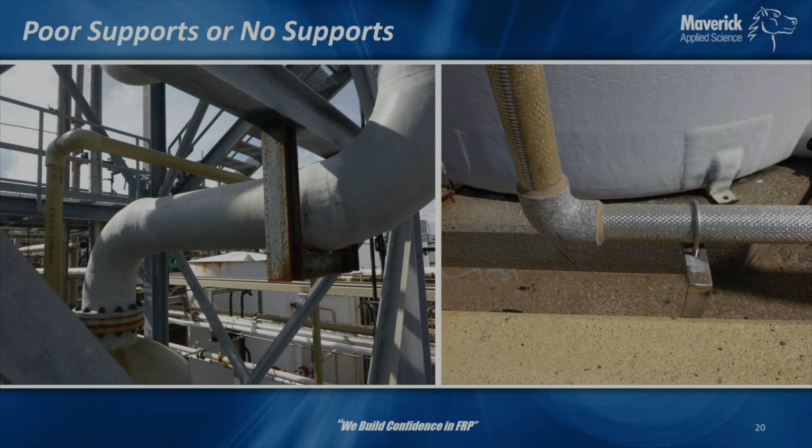But the big thing here is that you've got a U-bolt here, and again, sitting on steel, really, we should have that protected with the shield. U-bolts are fine if we do those sort of things, but we really want to see those shields in there because it makes point loads on the pipe. You have the chance to have abrasion. Shields are like the cheapest support you can get, really easy to make, and not hard to install either.